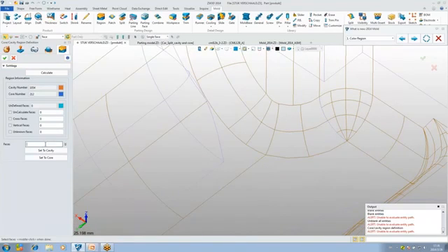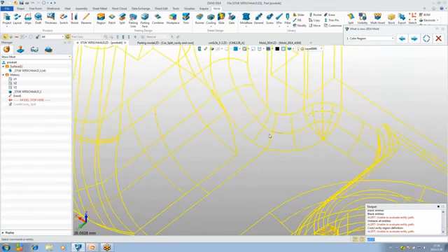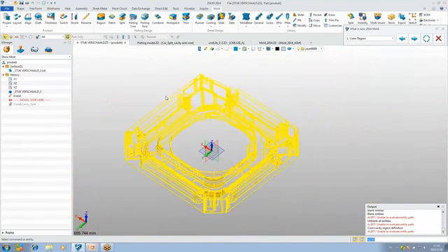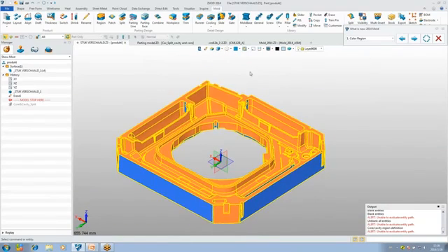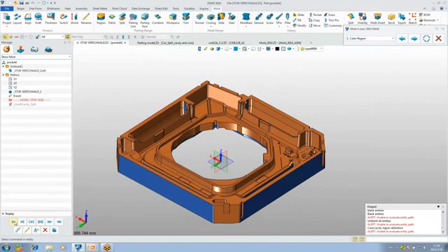Okay, just go to the face input field and select this small face. It should be set to cavity, so we set it to cavity and click OK to exit the command. Jump to the shape mode. Then play the history to drop to the end.